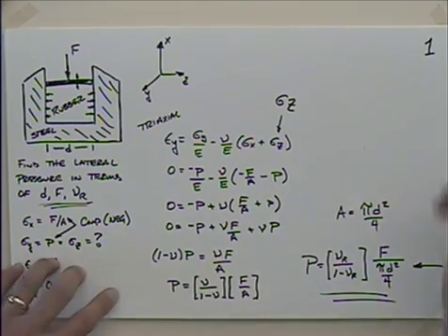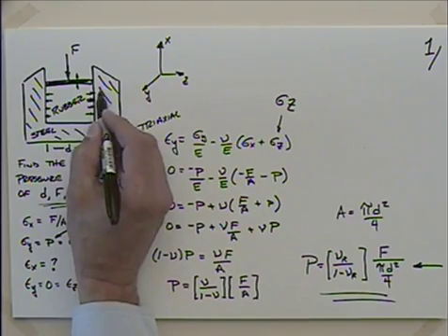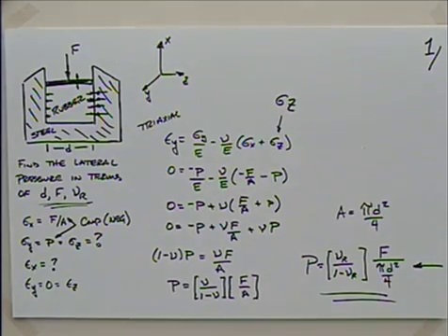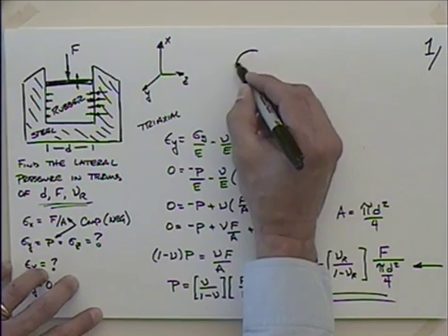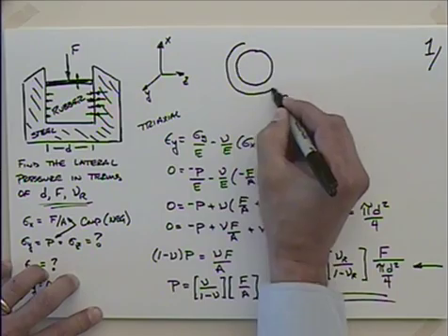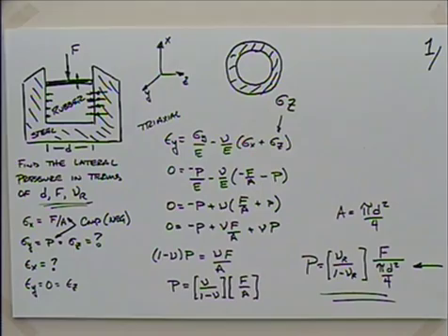That's the pressure on the wall on the outside of it. That's the pressure that the rubber is pushing onto the steel with, and of course would then be the pressure that the steel is pushing back on the rubber with. It would be the cross-sectional area of that rubber, it wouldn't be the total surface area around. Yeah, if we look at a top view of this thing, the top view looks something like this, where we have this steel container and then we put that plug in there of the rubber. Other questions?